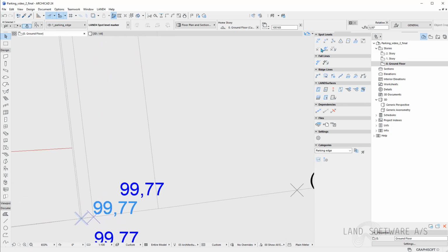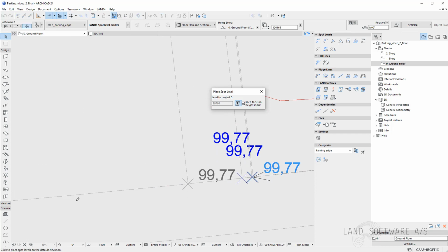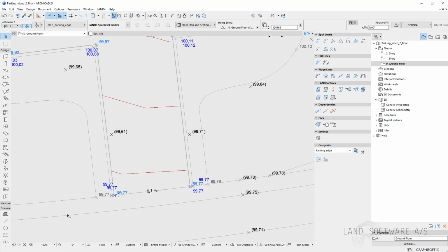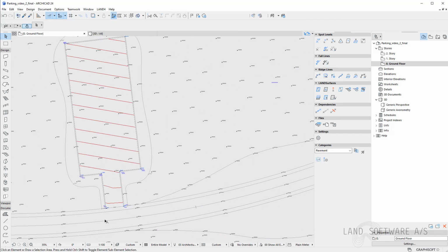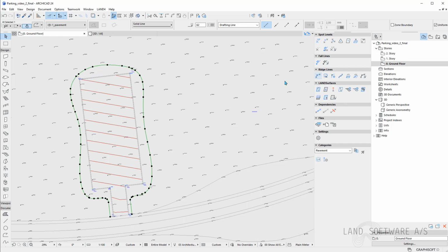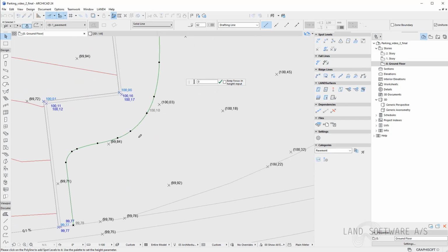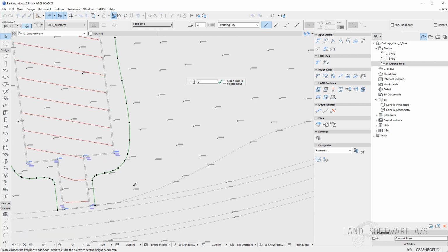And I will also use the gravity to place a spot level at the intersection with the road. Now I can start constructing my pavement outer boundary. So I again selected and created it as a ridgeline, and start snapping all the spot levels I have just interpolated.